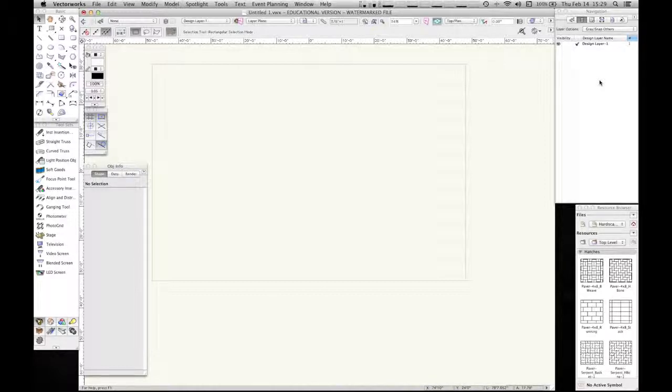In this case, we're going to create one new layer, and we're going to import a PDF of the ground plan of Ethington Theatre. This ground plan is actually to scale, and when you import it, you'll be able to drag it, and it is perfectly sized to this piece of paper that you have here, your ArchD settings, 36 inches by 24.